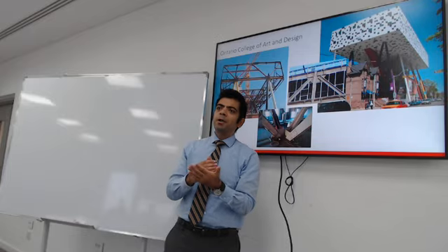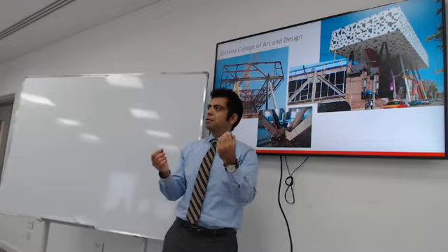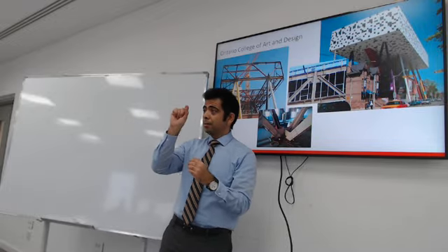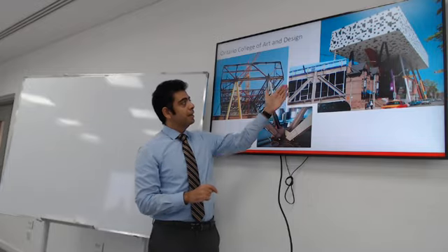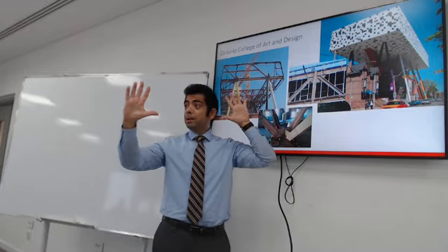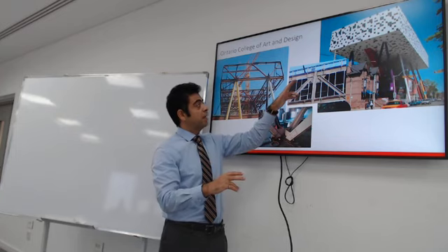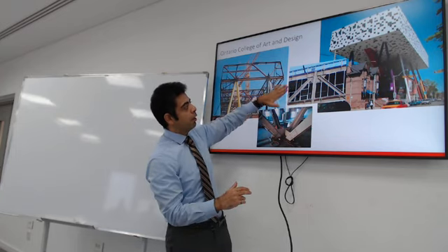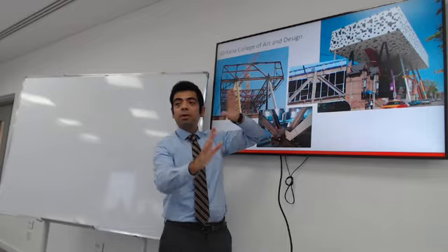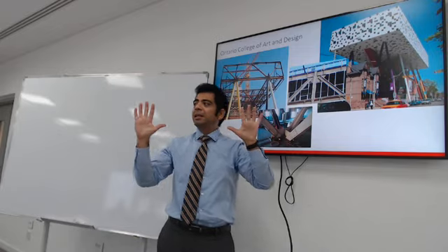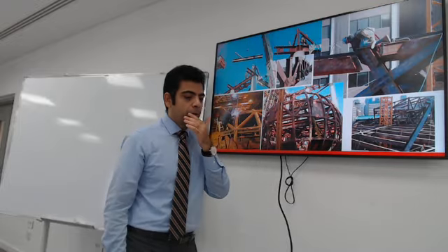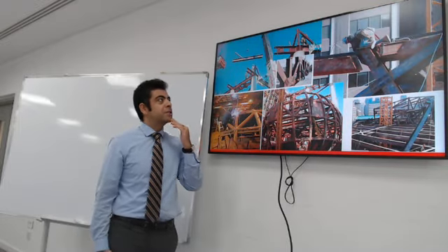In Structure Analysis 1, you'll probably remember we analyzed stresses. At the joint, we assumed it as a node, as a point. In reality, the intersection of the truss joint has big geometry actually, and you take into account how far you take the connection away and consider these plates, these gusset plates that hold the connection together. This is what I was talking about, the construction process.